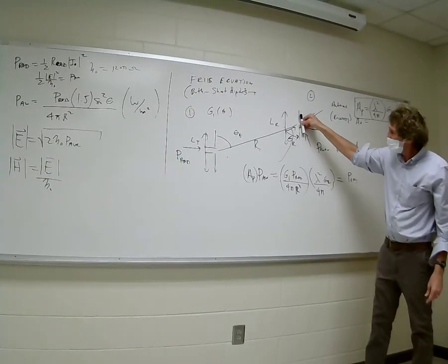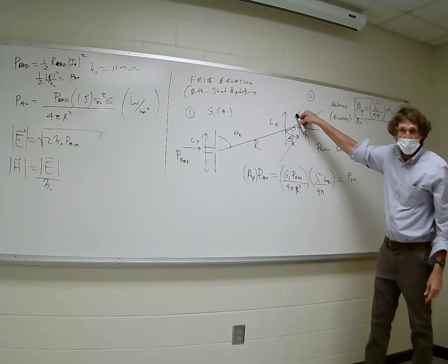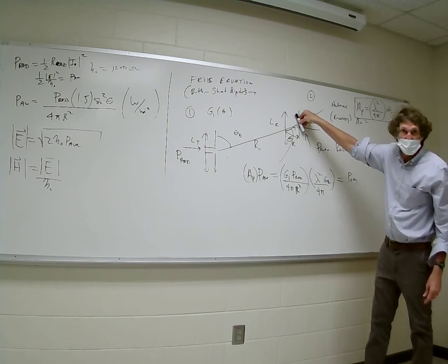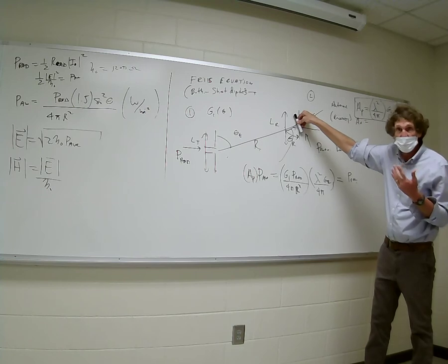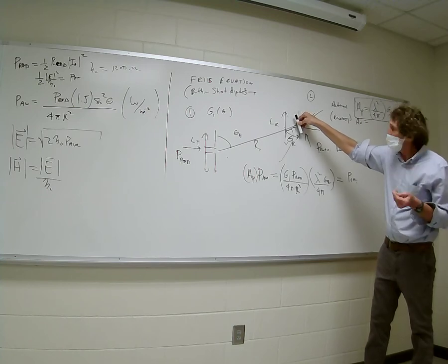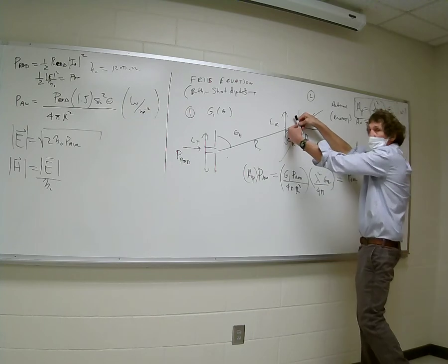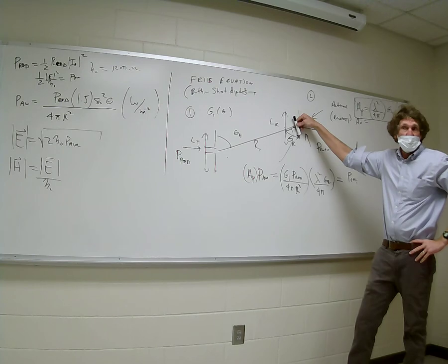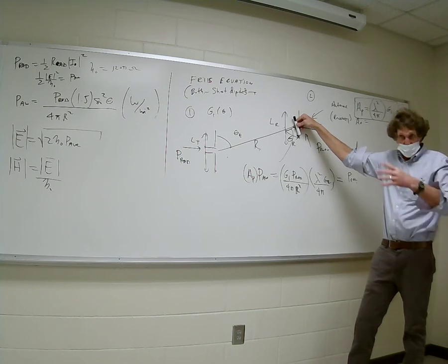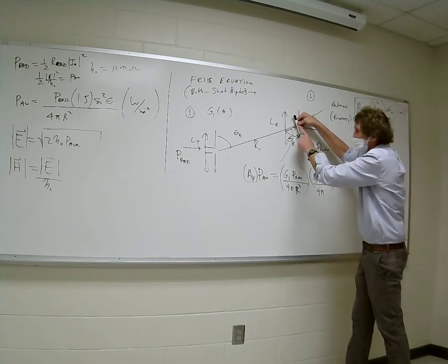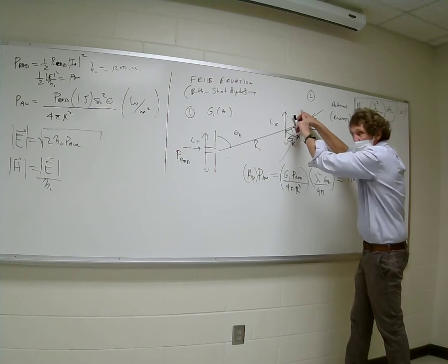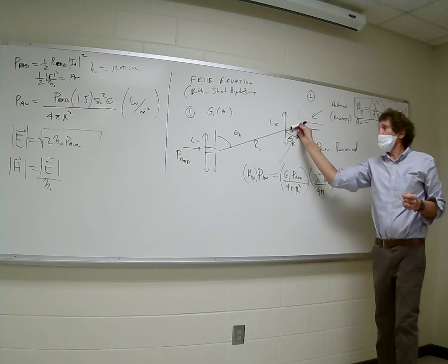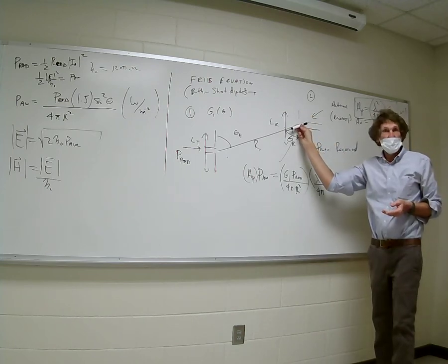What happens if I do this to the amount of power received? Just think about it. If I take the antenna from vertical and I do this, does the power go up or down? Well, y'all see that this thing is more perpendicular with r? The power goes up. You all see that? It's actually going to go up as the gain is a function of that, because the angle between the axis of the antenna and the radius vector would be 90 degrees. Do you all see that? And if I went like this, how much power would be received? 0. You all got that.